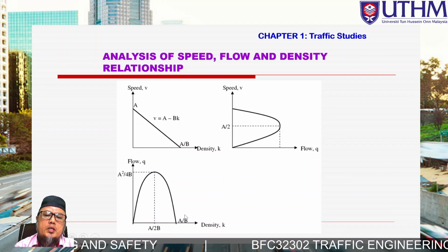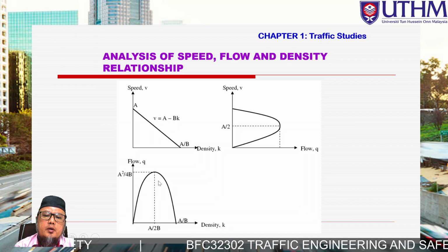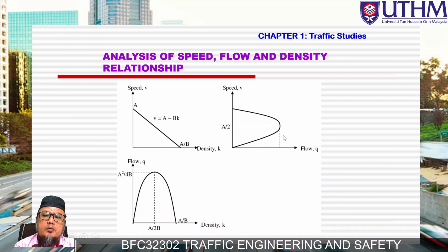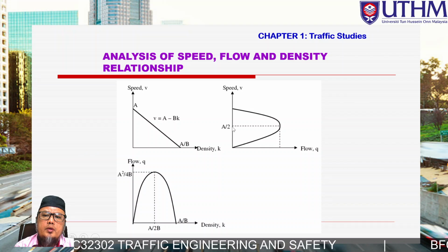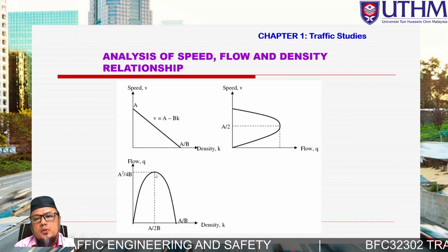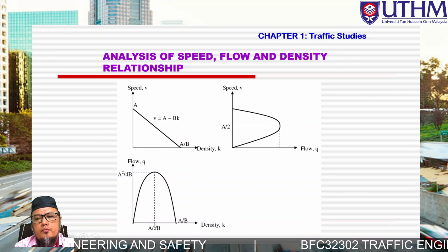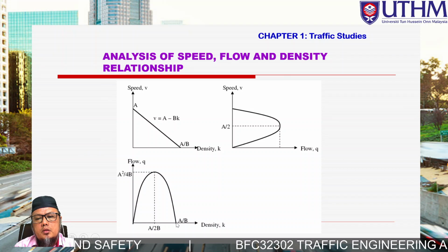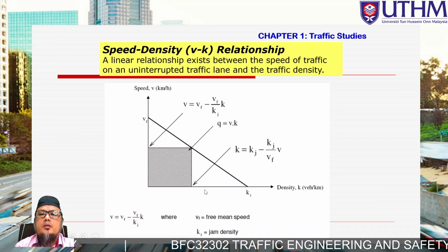So this one, flow and density. At the optimal flow, they have half of the density value. So here, optimal flow provides half, or V optimal, of the free flow speed. From the maximum or optimal flow, there is an optimal value for density. This one is considered jam density, no moving vehicle at all. This one is considered the optimal one.